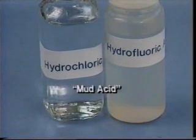This mixture is commonly called mud acid. The optimum concentration of HCl and HF mixtures varies and should be based on acid solubility tests of the formation. In any case, hydrofluoric acid should never be used in any formation with a carbonate percentage above 20%.